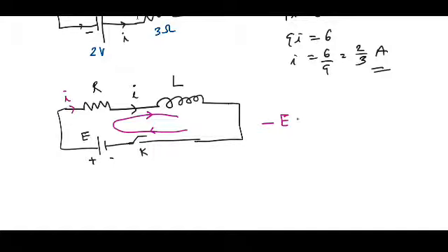Therefore, the voltage is positive, IR. Then the voltage developed across the inductor is L di by dt. If we just press the key, a current starts to flow, and also if I just open the key or break the circuit, at that time also there will be a current variation in the circuit. Otherwise the current will be steady.